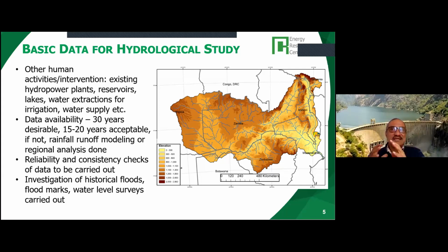It is important because such a huge structure, a reservoir, if there is some damage, it can affect the lives and livelihood of many people in the downstream area. For mini hydro projects, you don't need to design for such high floods, because even if it is damaged, you have economic losses, but losses of death or livelihood or lives of people is very less.